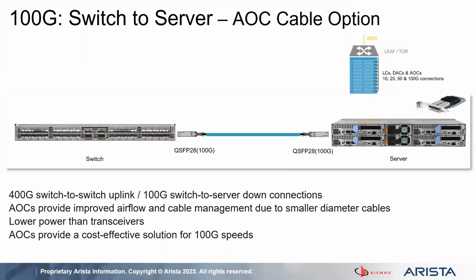This can go a little bit farther. We typically recommend up to maybe 30 meters, so it's in that window of above 5 meters up to 30. Once you get too far, even at 30 meters, you're probably doing structured cabling. But it is a good option that we see out there as well.